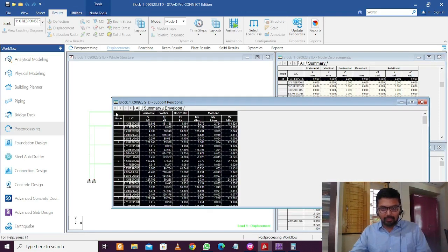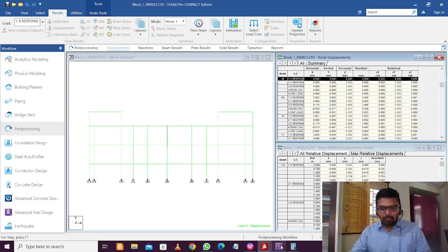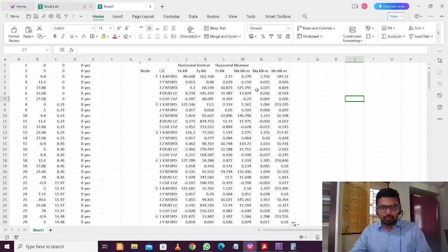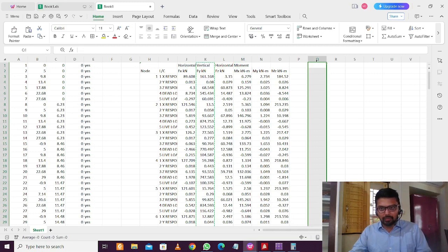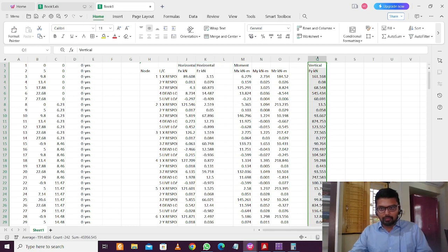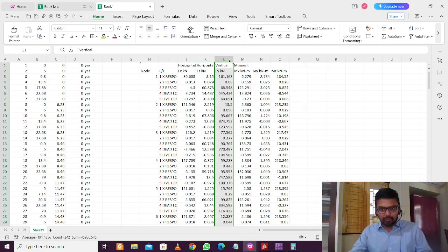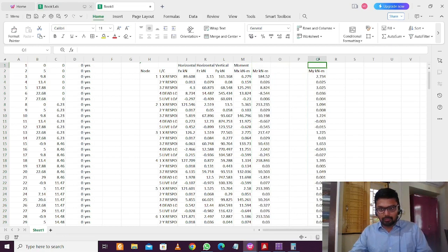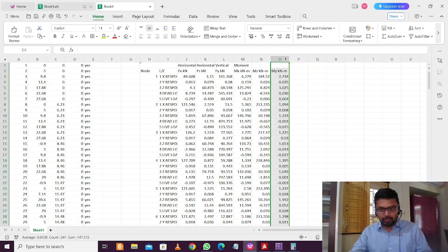and click on copy. After you click on copy, open your spreadsheet file, click here and click on paste. Now we already know that these are interchanged here, Y and Z. So just interchange this with Control X, Control V, repeating for each column.